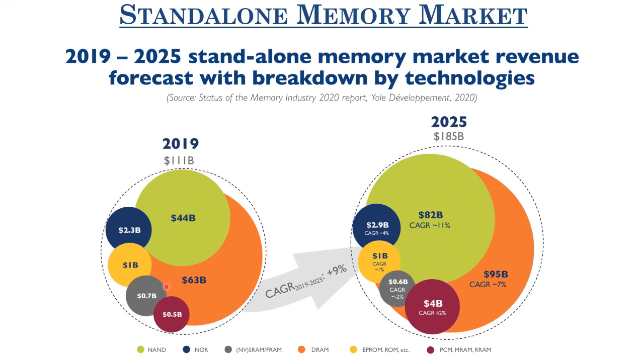However, if you look at this market of SRAM, non-volatile SRAM or basically SRAM, you see that there is a reduction in the overall revenue. The thing is, companies are trying to do away with these SRAM kinds of memories because they require a large number of transistors, let's say 6 transistors. And as I told, in VLSI, cost is actually proportional to area raised to power 4. So people are trying to do away with SRAMs even for cache.